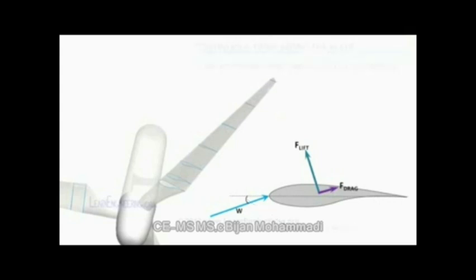Wind condition can change at any time. So it is also possible to rotate wind turbine blades on their own axis, in order to achieve the optimum angle of attack with varying wind condition. This is known as pitching of blades. A clever algorithm, which uses wind condition and characteristics of the wind turbine as input, governs the pitch angle for maximum power production.